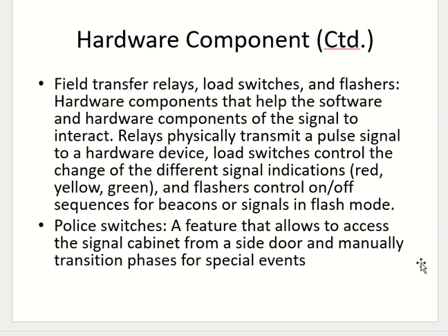And then we have the police switches. We know that, right? The only thing which we know about signals. Clear? They can manually control the sequence of the signals. They are not controlling the lights; actually, they are controlling the sequence. It's not like red here, green here. They are not doing this. They have their switchboard from where they initiate this direction next, and a signal will perform its sequence to give the next green to that direction.